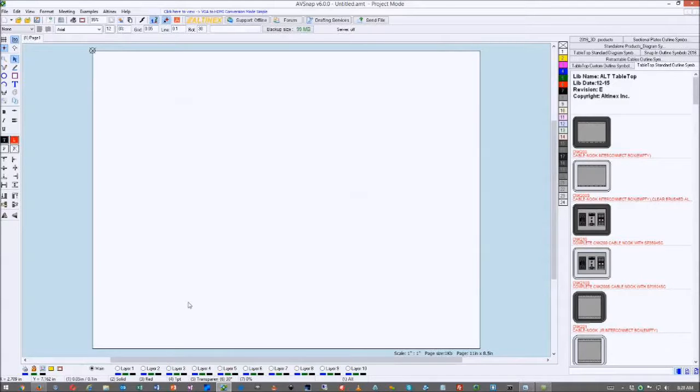First, you can name the layers anything you want. So right-clicking, right mouse button, on the layer text will give you an option here. In this case, I might say plans or drawing. That may be background. I can also make another layer called audio routing, audio. You can also call another layer video, video, and you can also say maybe power. I do this a lot if I want to show multiple things on the same drawing and switch between them.